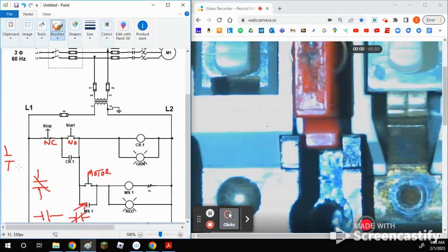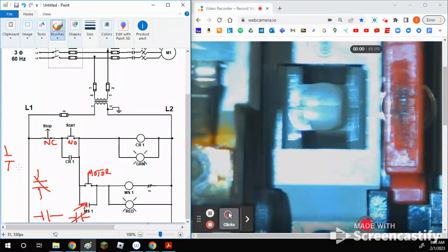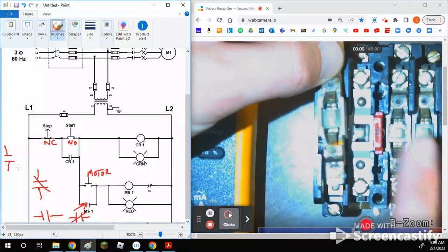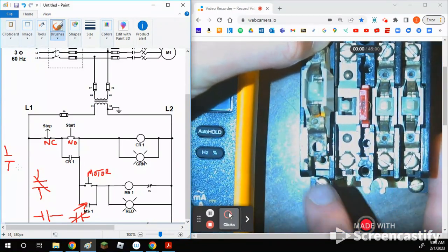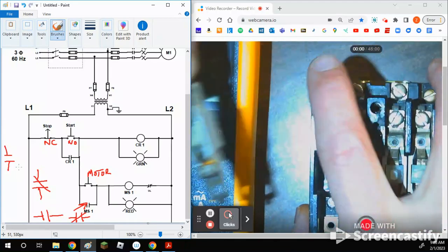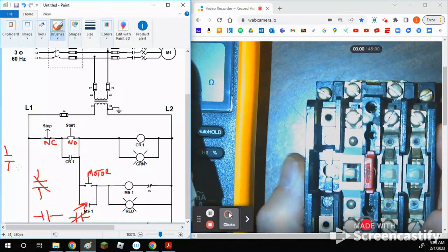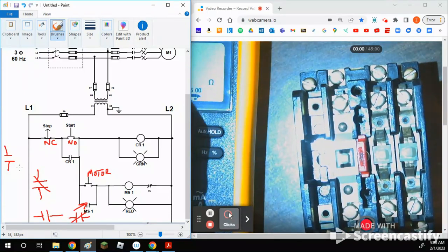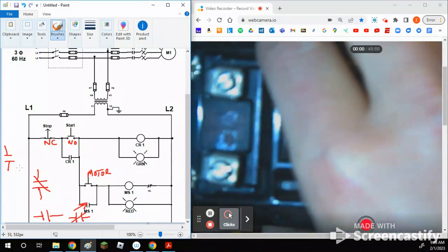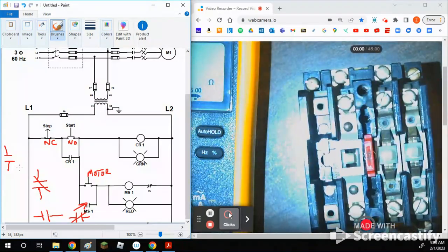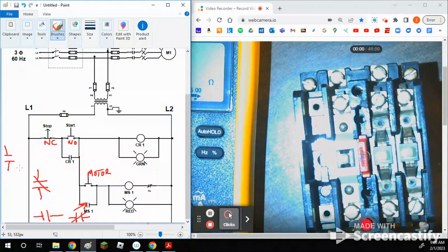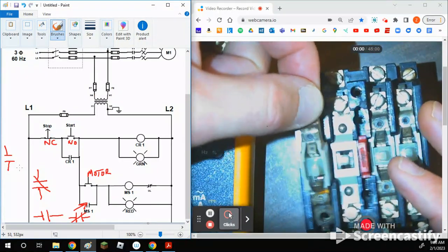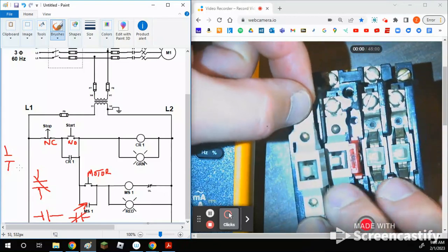To get at the coil, if you were going to replace the coil or see how this thing operates, after you get the cover off, there's 4 screws, 2 here and then 2 on the top to take the whole top casing off, and that will show you what the coil looks like underneath. It's the same thing as this motor starter coil. Remember I pulled that out, and it's like a figure 8. It's got a couple pieces of iron that are sticking through the holes. Same kind of thing. But that is how these control relays operate.